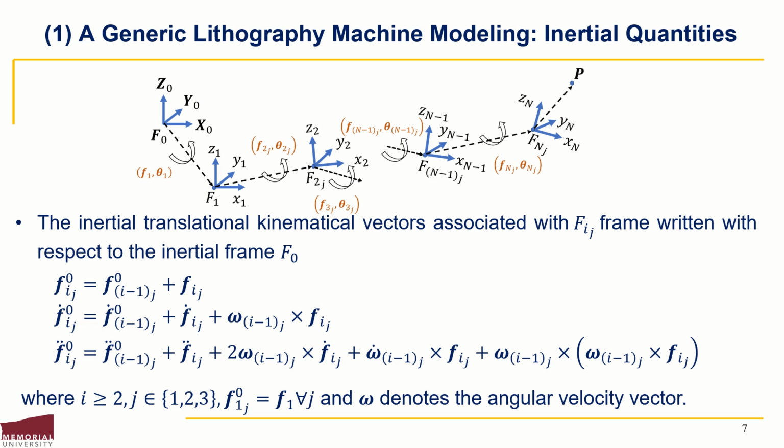According to this figure, each chain in the machine consists of a number of stages whose body fixed frames are attached to the center of gravity of their corresponding stages. Defining a suitable generalized coordinate system, both the linear and rotational motion of a chain can be obtained.